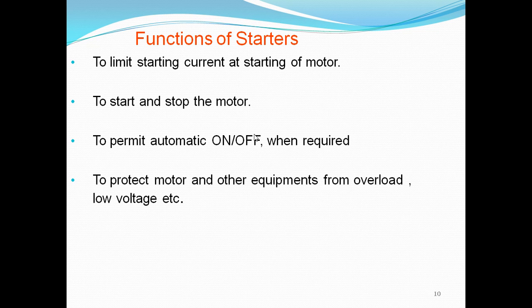Why? Because speed is 0, so slip S is 1. When speed is 0, slip is 1. So the induced EMF is equal to the starting EMF, that is E2.